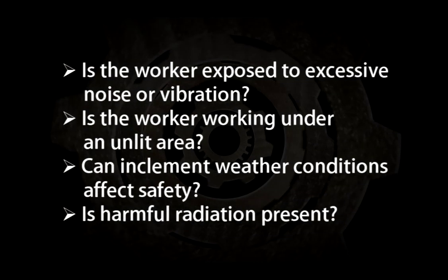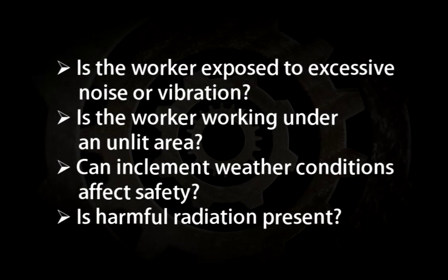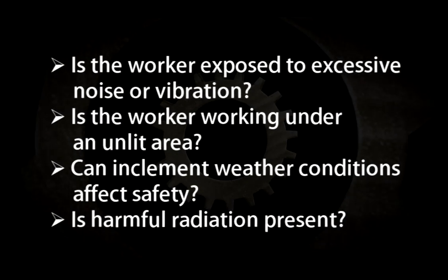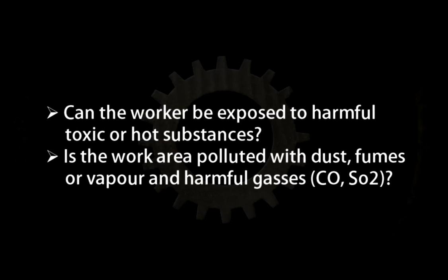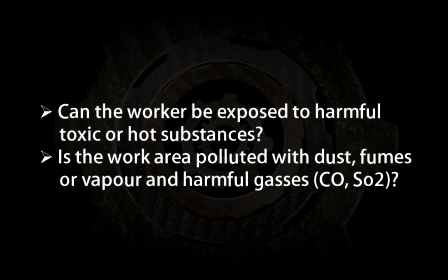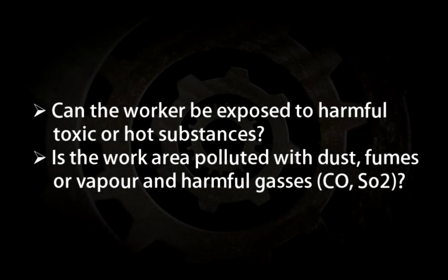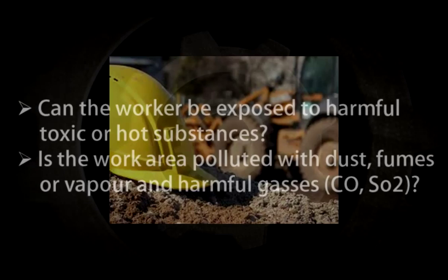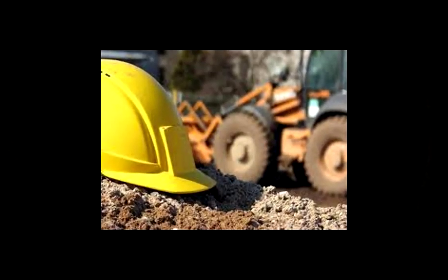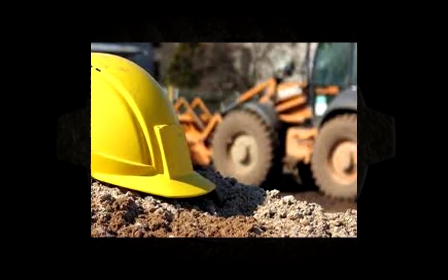Is a worker exposed to excessive noise or vibration? Is a worker working under an unlit area? Can inclement weather conditions affect safety? Is harmful radiation present? Can the worker be exposed to harmful, toxic, or hot substances? Is a work area polluted with dust, fumes, or vapor and harmful gases, such as carbon dioxide? Based on the above and sound judgment, potential hazards could be listed against each work step.